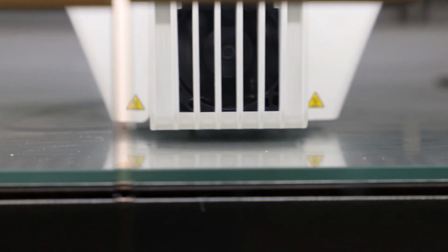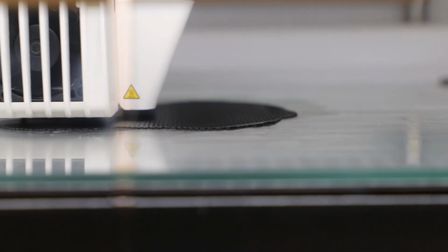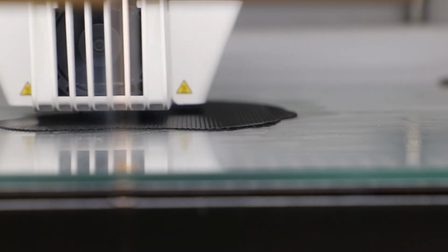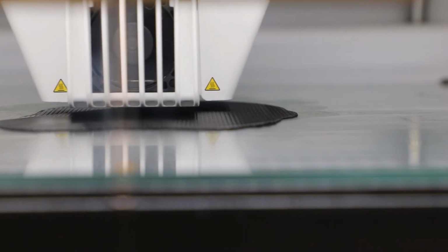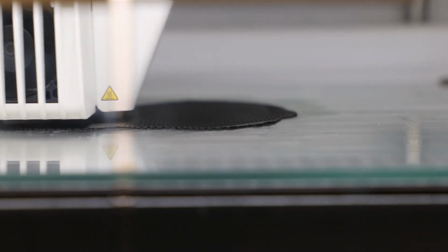The machine will zero the axis for its 3D printing, and once it's done that, it will commence laying down its first layer. So it's probably a good idea to stay with the machine to make sure the first few passes of the print are laid down properly, just to make sure that it sticks to the bed and the file is running okay. So when you're happy that all is good, you can leave the print, might be overnight or throughout the day, and come back when your time is up.